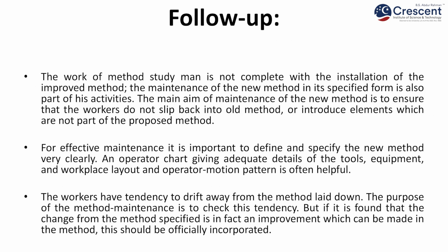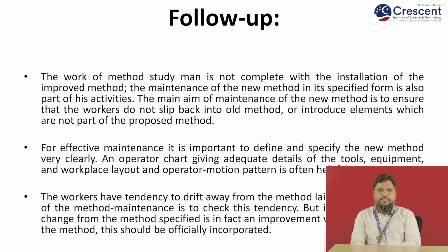After we install the method, we have to continuously monitor it. So, follow up is important in method study. It is an inherent human characteristic that he will slip back towards the old method. So, we have to follow up the installed method continuously.